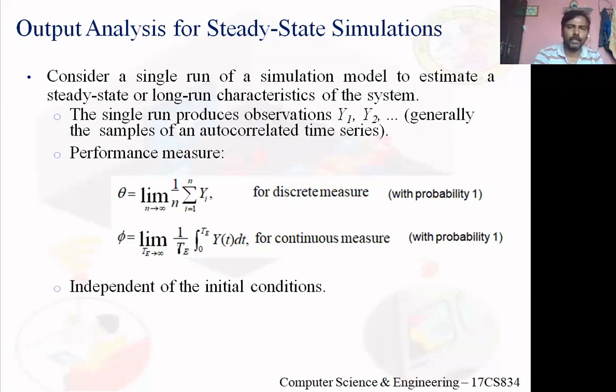Clear with this? In non-terminating simulations, we are observing the cycle time of an infinitely large number of parts, because the simulation is run for an infinitely large time. So we need to sum the cycle time of all the parts, then divide by n. And in this case, n is infinite; it approaches infinity.